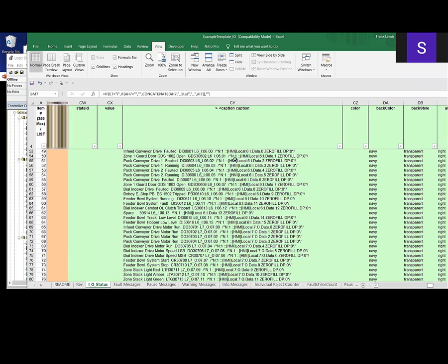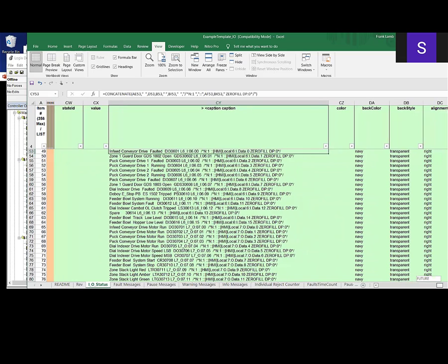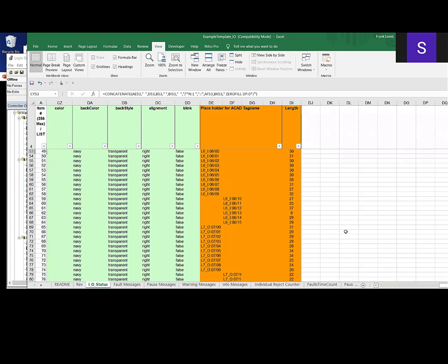It also created this, and this was for PanelView Pluses. And a PanelView Plus had a structure like this. If I were to take my PanelView Plus push buttons and items on the screen and export them, they would be exported like this. This zero fill would say, okay, I don't want a bunch of empty space after the name of this message or whatever. And the background color would be navy blue, and it would be a transparent back style and all that kind of stuff. So this spreadsheet saves a ton of time.